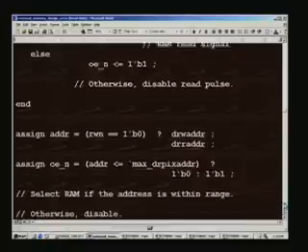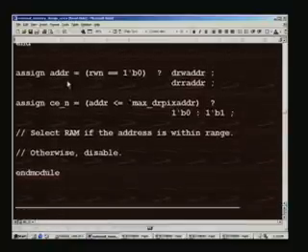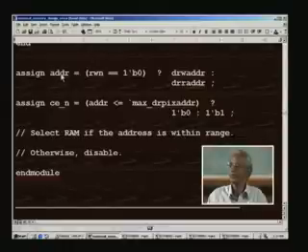Then at this step here, what we need is a single address to go to the actual RAM, and that address may be either a read address or write address, and that depends upon the read WN control. If it is 1, it would mean read, that is here, and if it is 0, it would mean write here. So when it is 0, it is write, therefore this condition being satisfied, it will return 1. For 1, this is the condition, this is the mux that you are already familiar with.